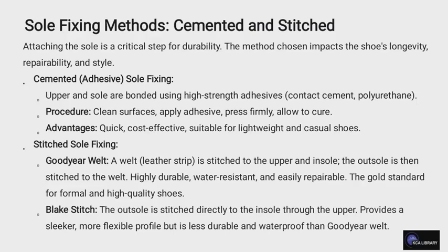The upper and sole are bonded using high strength adhesive, in terms of contact cement or polyurethane. The procedure is: you clean the surface, apply adhesive, press firmly, and also allow to cure. The advantage of this method is that it's quick, cost effective, and suitable for lightweight and casual shoes.